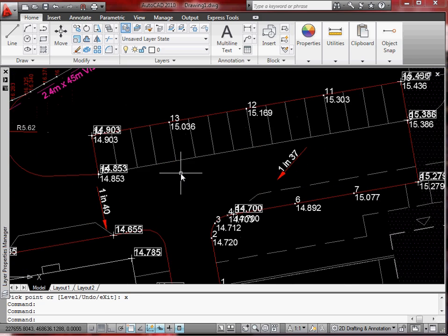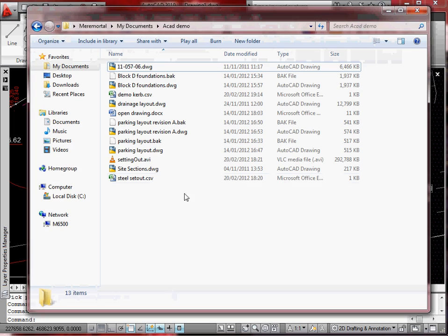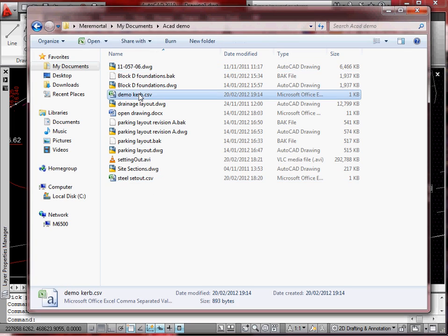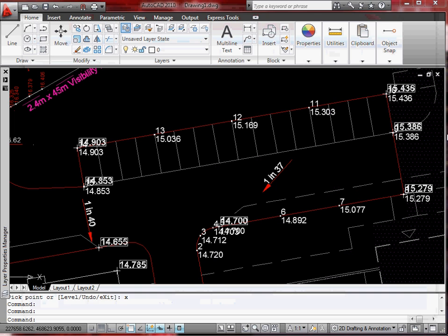So obviously you can print that out, take it on site with you, and if we open up the curves, there you can see there's the point numbers obviously corresponding to the drawing. These are the heights, and this tells you whether it was an input level or interpolated level. Not that that really matters, but you can upload that to the machine, print your drawing out, laminate it if you can. Some easy setting out. Okay, hope that is useful.